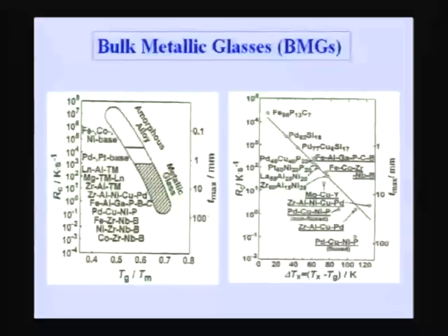One can do this in a ternary system or a quaternary system, identify all those compositions which have highly negative enthalpy of mixing, make only those few compositions and then check whether they become easy glass formers, and in most cases they would become easy glass formers. So these are some of the predictive kinds of criteria, and there are a number of people in the world who are trying to develop this kind of predictive criteria. Otherwise the existing criteria are these.